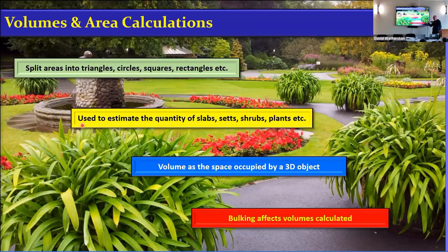And again, you can't just buy 10 cubic meters to replace it, because it's not going to be 10 cubic meters. You need to ask for 12 or 13 cubic meters, right? Because you're taking that material that's got holes and spaces in it to compress it down for your final design. Your design was based on 10 cubic meters finished article.